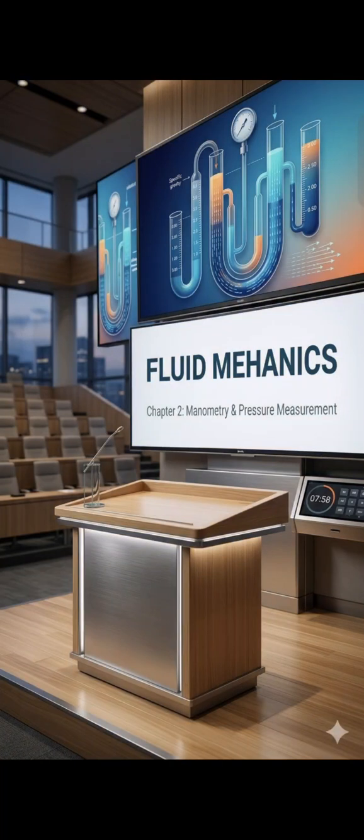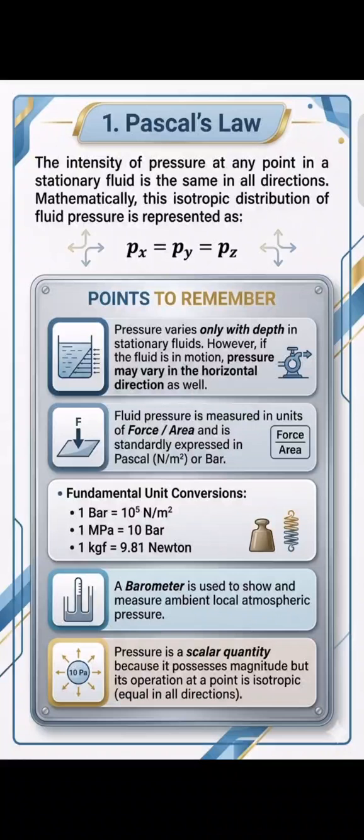Fluid mechanics, manometry, pressure measurement, Pascal's law. The intensity of pressure at any point in a stationary fluid is the same in all directions. Mathematically, this isotropic distribution of fluid pressure is represented as Px = Py = Pz. Pressure varies only with depth in stationary fluids. However, if the fluid is in motion, pressure may vary in the horizontal direction as well.